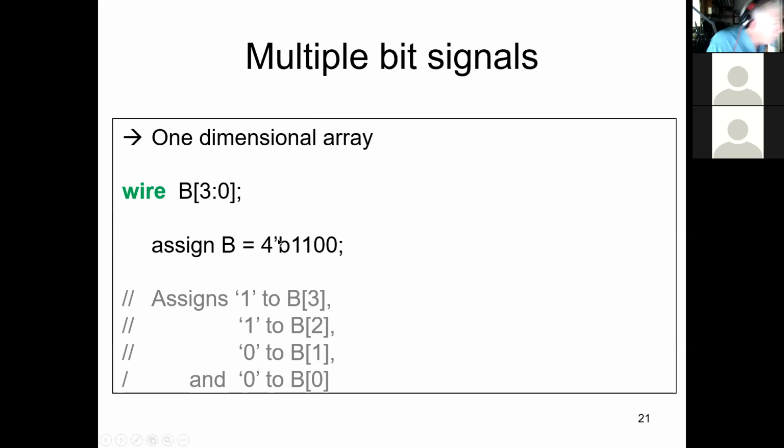And you can also do 2-dimensional arrays. One of the things to keep in mind with 2-dimensional arrays is they cannot be passed in parameter lists. At least, I think that may be an upcoming change in one of the next versions of Verilog coming out, so I have to double check to see if that's been changed. But last year, you couldn't put multi-dimensional arrays in a parameter list. So we'll see. I think they are going to change that eventually.